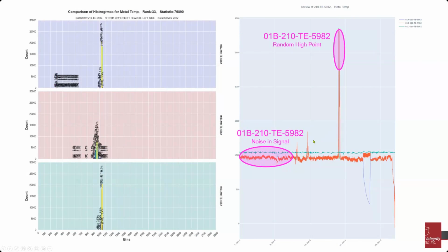And then you'll also see spikes up to unrealistic temperatures, 2500, 2600. So these are cases that you just have to deal with in the damage monitoring system to flag as potentially bad quality data, and to alert the user, this may be suspect, investigate it. And so one of the things we implemented is a way to discount or remove these events.